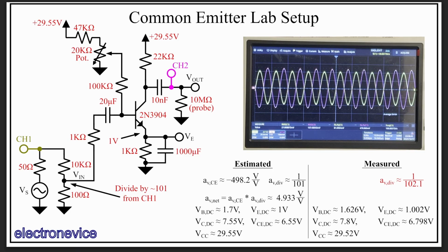Here I've reconnected the divider to the rest of the circuit, and we have the two oscilloscope channels set up as they're shown in the schematic again, so the circuit is properly set up as shown. Sending a 100 Hz sine wave through the system with the input amplitude set so that the peak-to-peak voltage on the output is roughly 500 millivolts, we can now calculate the overall gain of the circuit. We see that the input in yellow shows a peak-to-peak voltage of about 81.07 millivolts, with the output in magenta at 477.8 millivolts. This produces a gain of approximately 5.89 volts per volt.